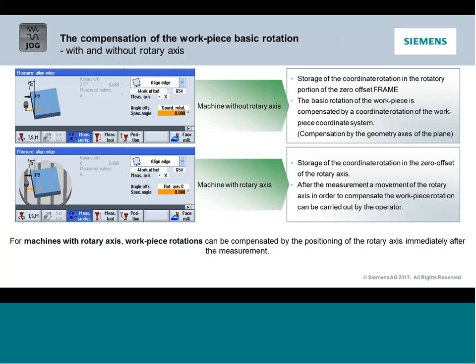Well, even if I don't have a physical rotary on the machine, I can write it to the coordinate system and let the machine spin the coordinate system to align itself to the part. So I always like to say that we allow the machine to kind of align to your process instead of forcing you to align your process to our machine or our control, our functionality.